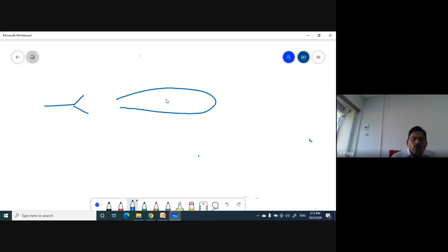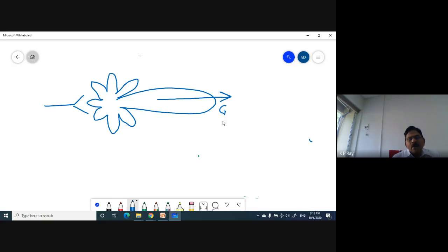So if you plot the radiation characteristic in three dimensions, from all different directions, the angular three-dimensional spread of radiated power is known as the radiation pattern. So here the beam is maximum. So then we say that the gain of this antenna is maximum. We say the directivity of the antenna is maximum, and then when efficiency is 1, then directivity of the antenna is